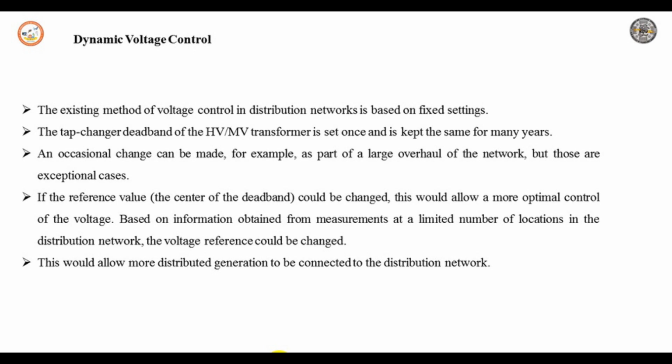This information is used to estimate the voltage profile along the feeder, based on which the optimal voltage at the main bus has to be determined.